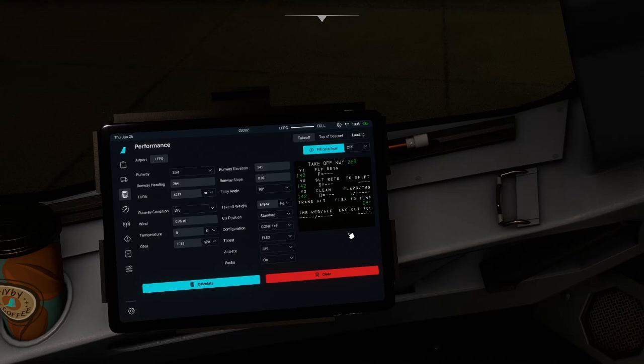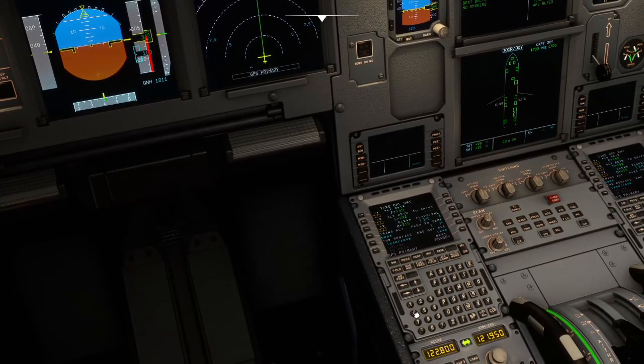Look, those are going to be good enough for now. So it's taking off at 64 tonnes, which is about right. A little bit of tail, but I'm not too concerned because I just want to get underway. So the V speeds are going to be good enough for our 4-kilometre long runway. She is not balanced field.